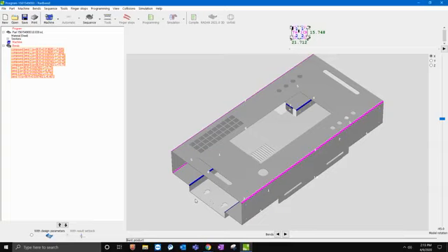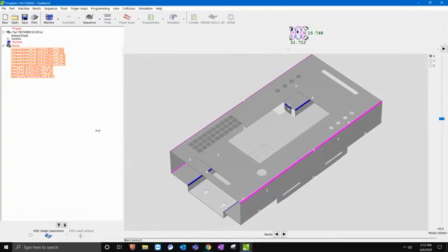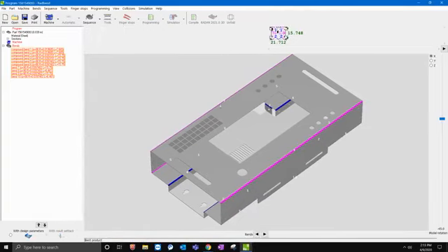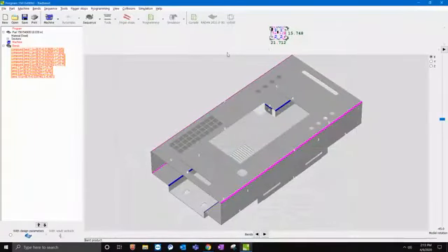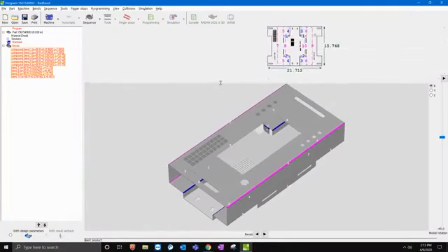So I've opened it up. I've got the file in here in Radbend for my sheet metal component, and you can see it's carried in my material thickness. Here's a machine. It's added some bends to each of these sections. If I come in here, I can pull the screen out a little bit so we can see, and I can pull this one down. You can see the steps of my bends there.